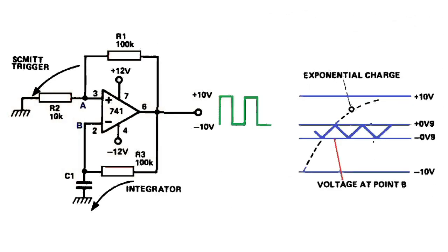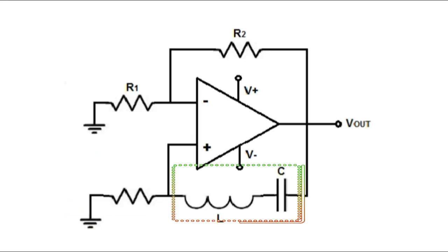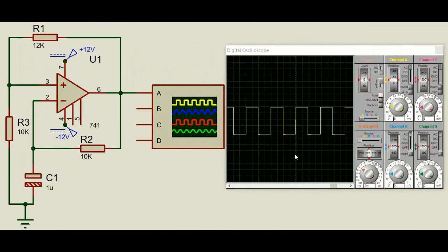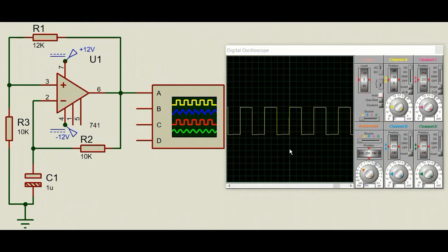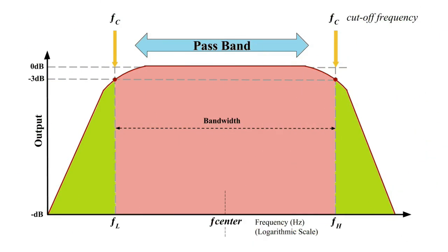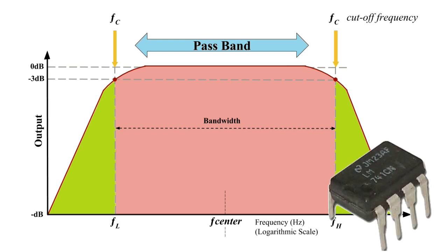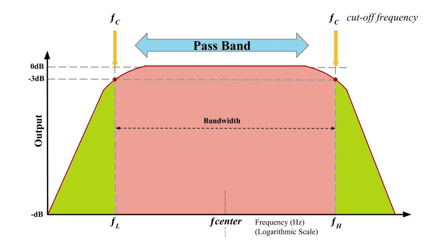In an op-amp oscillator circuit, an op-amp is configured with a resistor-capacitor feedback loop or inductor-capacitor feedback loop, which triggers the op-amp to go into an oscillating mode, generating switching on/off pulses from its output pin. The high gain and wide passband of operational amplifier ICs makes it possible for these units to work like an oscillator within a wide range of frequency.